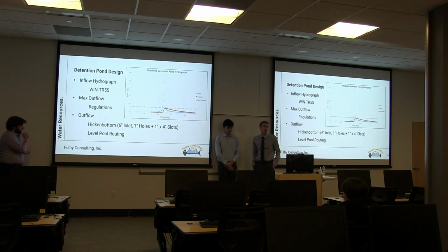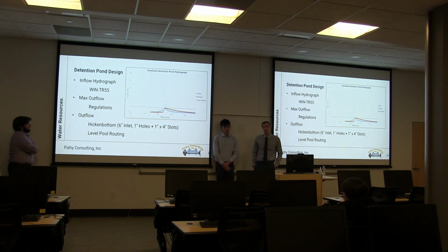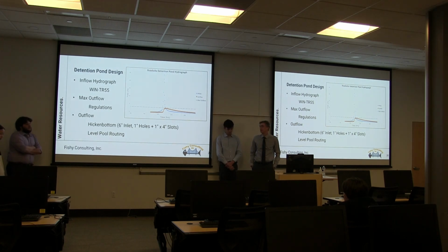For detention pond design, an inflow hydrograph needs to be produced using the WinTR55 computer program. So utilizing curve number, time of concentration, and rainfall intensity, the inflow hydrograph as seen in blue was produced.